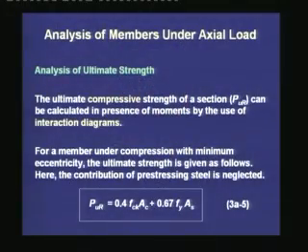Next, if we are calculating the ultimate compressive strength, then the expression in presence of moments can be found out by the use of interaction diagrams. Usually, compression members are also subjected to moments, like columns. Now, if we have to find out the ultimate compressive load in presence of moments, then we have to use the interaction diagrams that we have learned under reinforced concrete.